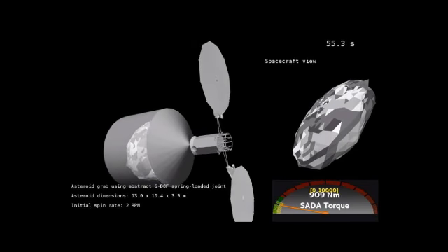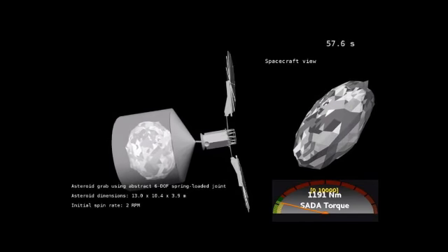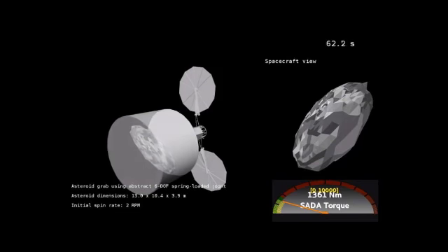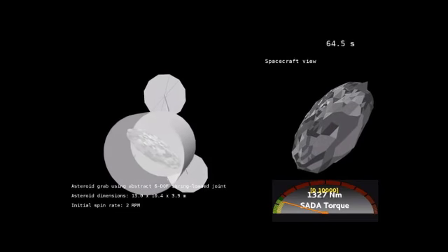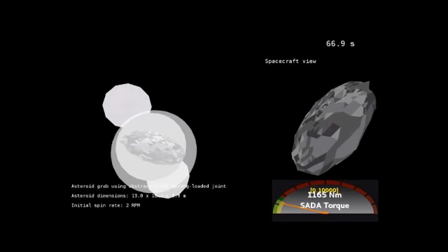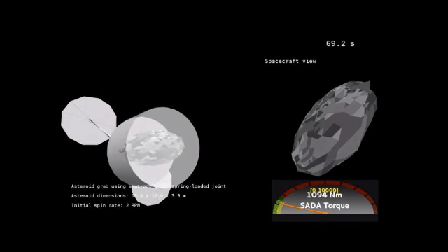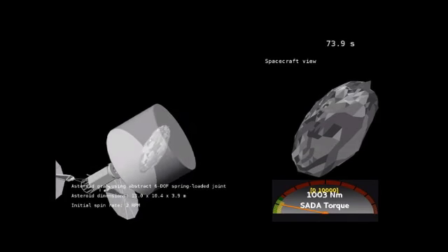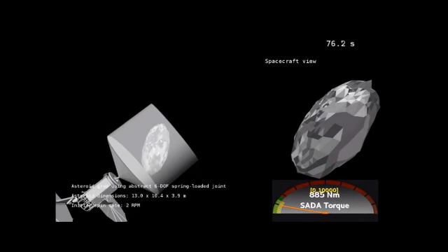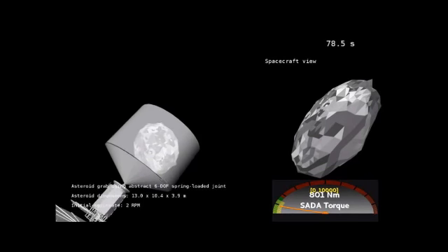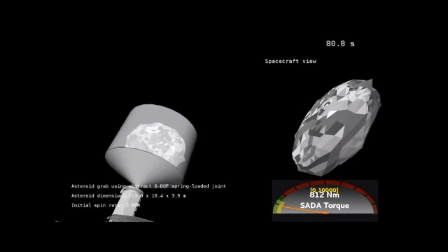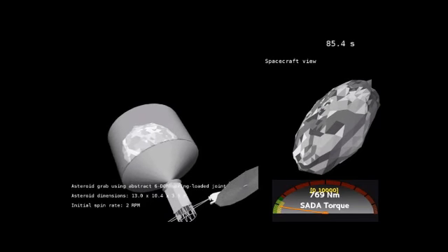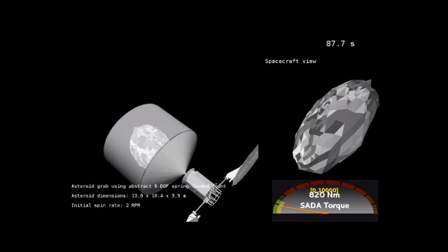And the other nice thing is that the RCS thrusters on the spacecraft are a large distance out, and this is a typical simulation result, that the RCS thrusters are far enough out from the belt line of the asteroid to give us a good lever arm with which to detumble and despin. And it only takes a relatively few newtons of force to detumble and despin this thing within a few hours. So amazingly, 1,000 tons spinning at 2 RPM, it actually doesn't take very much propellant to do that.